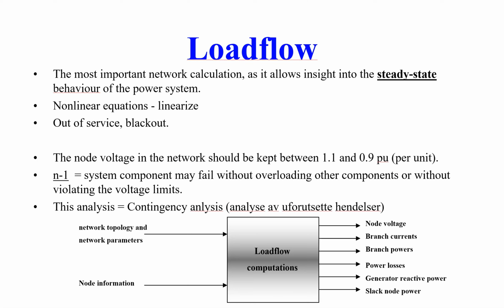So the load flow is the most important network calculation, as it allows insight into the steady state behavior of the power system. This is very important. We are not working now with transient dynamic systems, but we are looking at a snapshot of the flow of power in the grid in a steady state. We also should remember that the equations for load flow become nonlinear equations, and we often have to linearize.